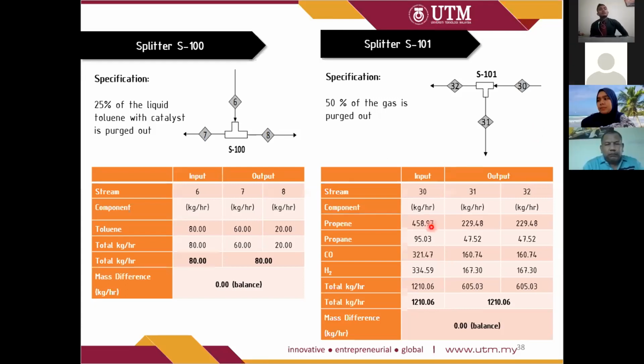Just a suggestion, make sure you recover the heat when you're pushing out the stream, because you can see the heat is actually very high. So later on when you do the treatment improvement, make sure you recover the heat. It's about 300 degrees Celsius. Okay.